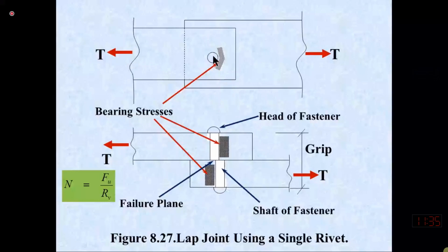A snug tight connection always has some slip, because we are not tightening the bolt with some specified pre-tensioning. This is the connection where we obtain the tightness by the full effort of a single person. That's why for a snug tight connection we always compute the modified slenderness ratio, because of slippage the actual slenderness ratio may be more, or the capacity will be less. A bolt joint in which slip resistance of the connection is also utilized is called slip critical.